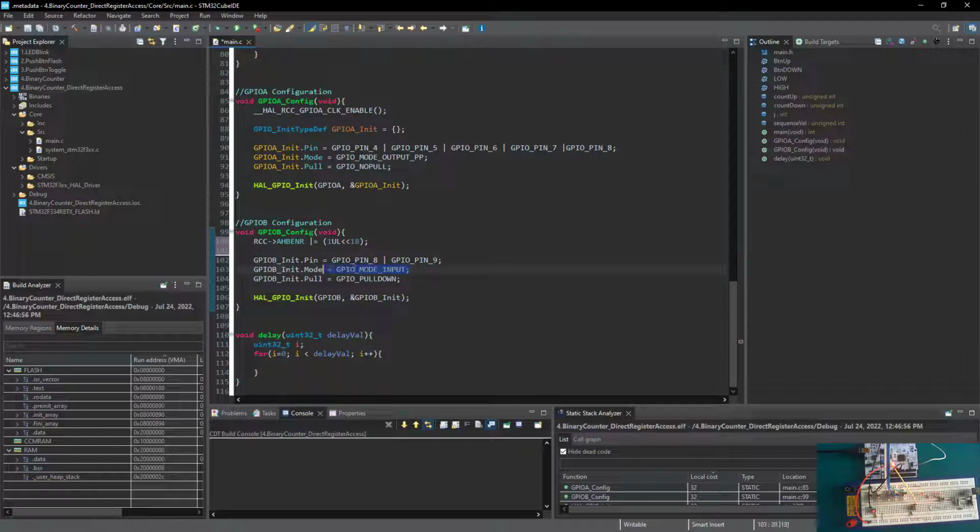We're doing it here with the library of the drivers, the HAL libraries. We were doing the mode and we say mode input. Now we're not going to be doing this anymore. So how are we going to now enable the mode? Well, we need to access this register also now on the GPIO B so that we can see how we're going to put it to mode input.